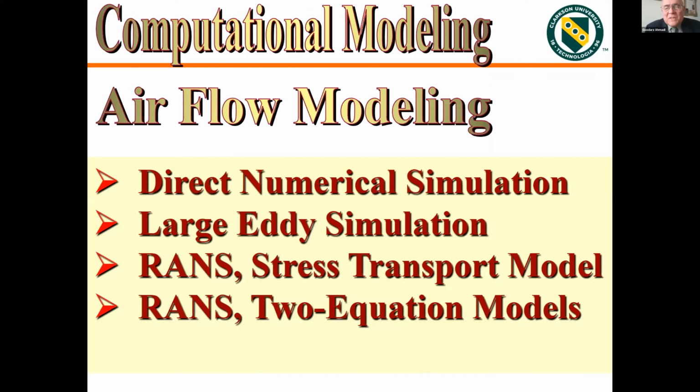Okay, I'll be talking mostly about a computer modeling approach, with some experimental verification, to look at how aerosol particles are transported in various situations. We first have to know how the airflow is moving, because the airflow carries the particles. For simulating airflow, in the atmosphere or any indoor area, there are different techniques. One is called direct numerical simulation, which is the most accurate but most expensive. So far, we could do small geometries with the power of the computers available to us.